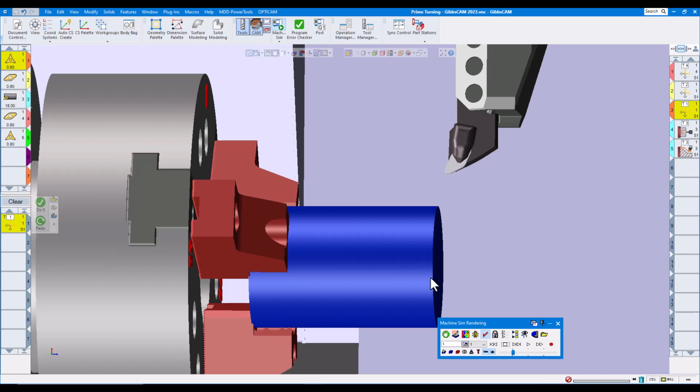Of course, just some caveats: you need some good jaws to hold the part. I don't know if I'd use smooth jaws. I would probably use serrated jaws or claw jaws. They hold the part very well in the tests that we have done. Or you could also bring the sub spindle up or tailstock to support it as well.